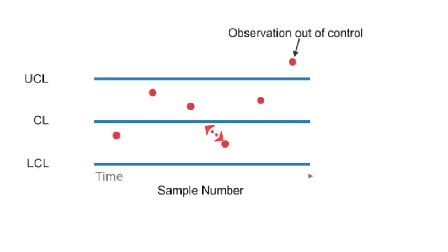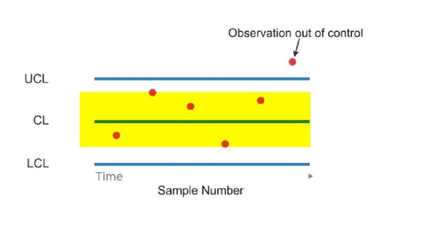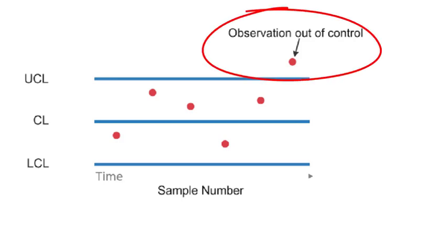This gives us a standard deviation. That is a standard amount of variance from that average line. When we do this, we can also see a range of variation. And this helps us to figure out the upper and lower control limits. Ideally, 95% of our measurements should fall within 2 standard deviations from that centre line. If we get a data point or measurement that is outside of our control limits, like this one at the top, then we should investigate the root cause of that problem. And there are actually software tools that can create control charts from a data set for you.